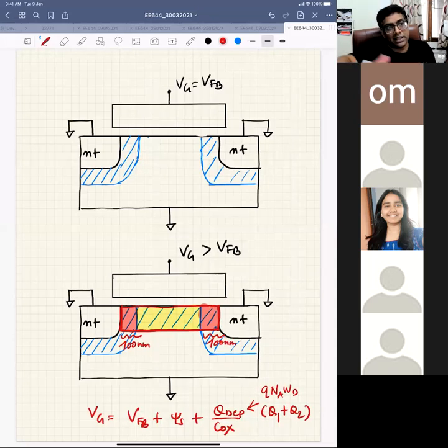And if your gate length is much higher, around 1 micrometer or so, then Q1 is contributed by the source and drain, and Q2 is contributed by the gate. If your gate length is very high, Q2 is more than Q1, so we can think that most of the depletion charge is contributed by the gate. But that will not be true when you reduce the gate length.